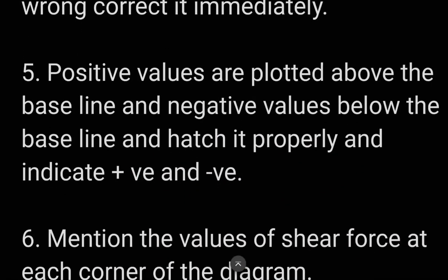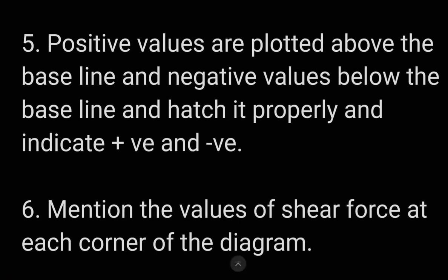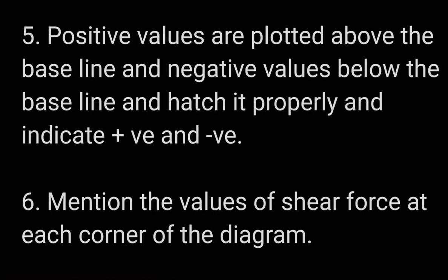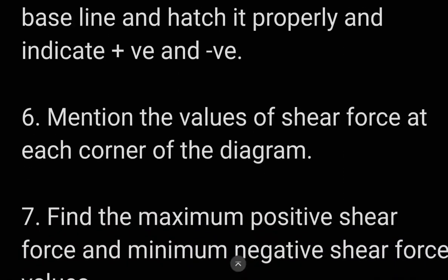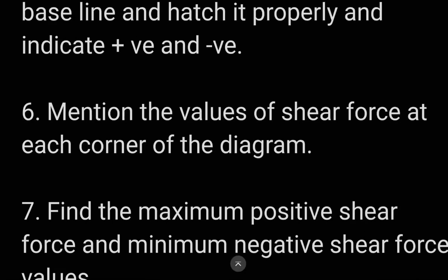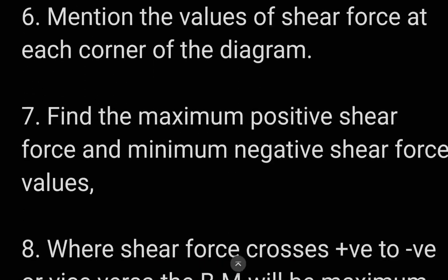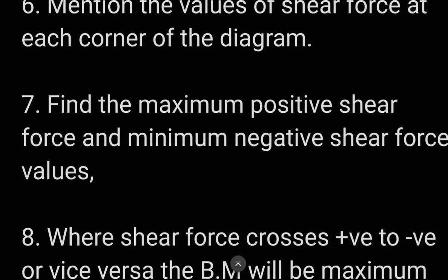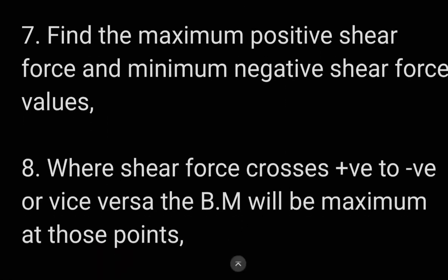Number 5. Positive values are plotted above the baseline and negative values below the baseline. Hatch it properly and indicate positive and negative. Number 6. Mention the values of the shear force at each corner of the diagram. Number 7. Find the maximum positive shear force and maximum negative shear force values.